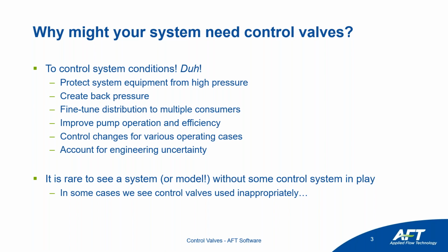The most common application might be if you're calibrating a system and you have both pressure measurements and flow measurements for your system. It can be very easy to fall into a trap where you want to specify both the pressure and the flow rate. However, if you try to specify both, you're really over-specifying the system. The hydraulic solver doesn't have anything to solve for.